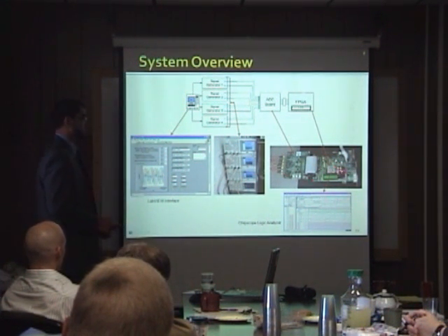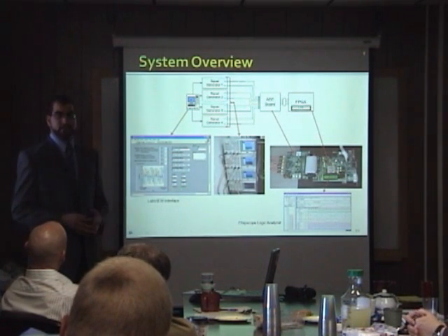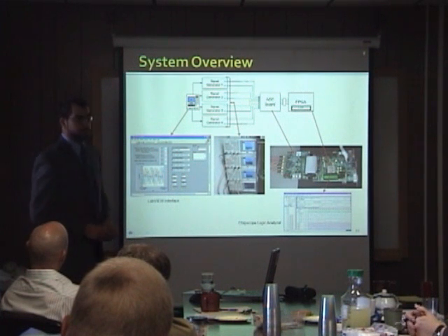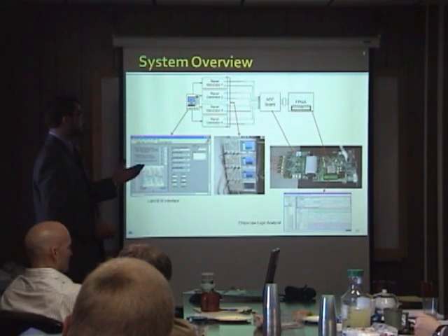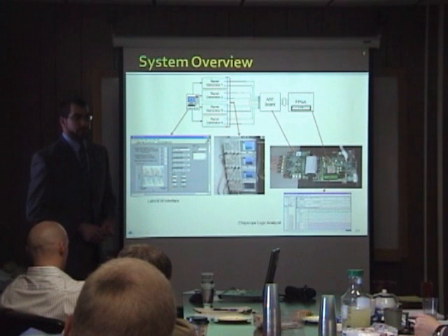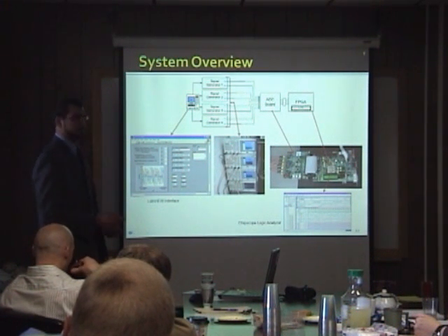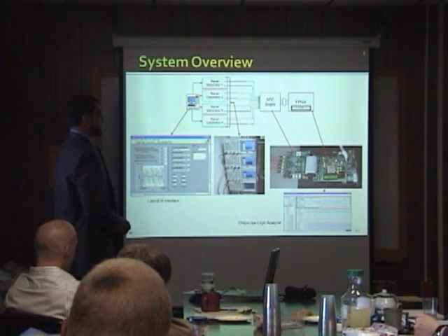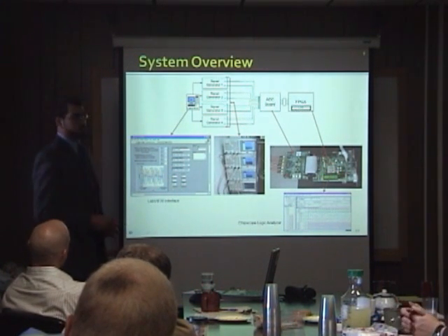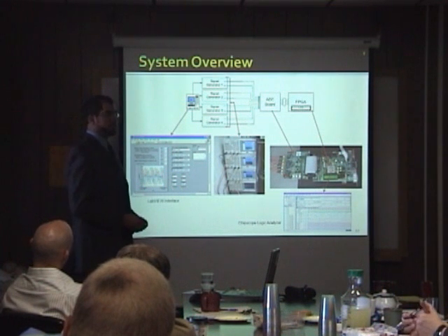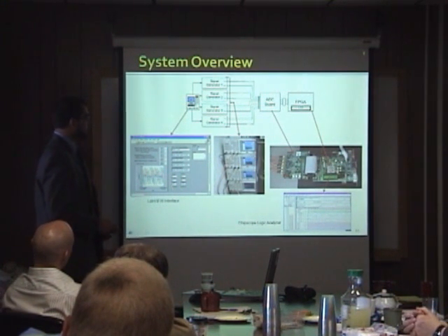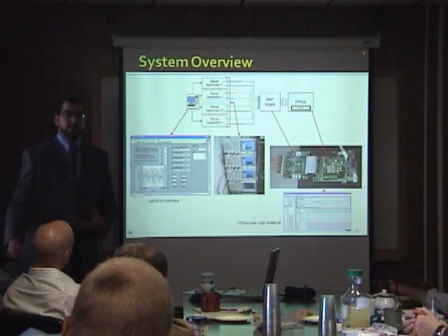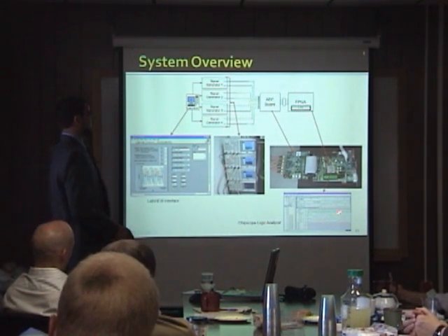And then we use the ChipScope logic analyzer, which is an analyzer that can be integrated inside the FPGA in order to monitor the internal signals and verify the functionality of the internal components. Traditional ways of testing systems using oscilloscopes and logic analyzers won't apply to the FPGA because the whole system is embedded inside the FPGA. So we need a system that can be integrated inside and send all this information to the computer in order to be analyzed.